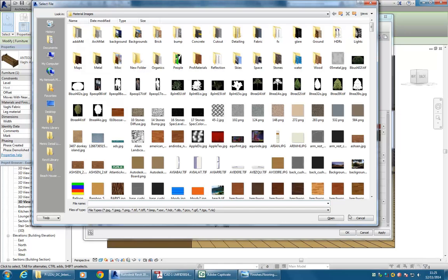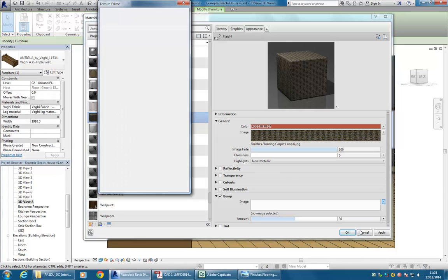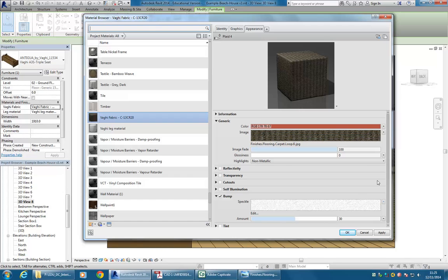And so here I'm going to just cancel the image selection and instead go and choose one of the presets that you have there. So you can choose any of those things like speckles to use a formula essentially to set the bumps. What is bumps? So it makes it look a bit 3D, like a textured pattern. Okay, so for things like fabric, that can be useful. And you'll see with bricks and things like that, it often has a bump map as well as the colour assigned. So just keep an eye out for those things.